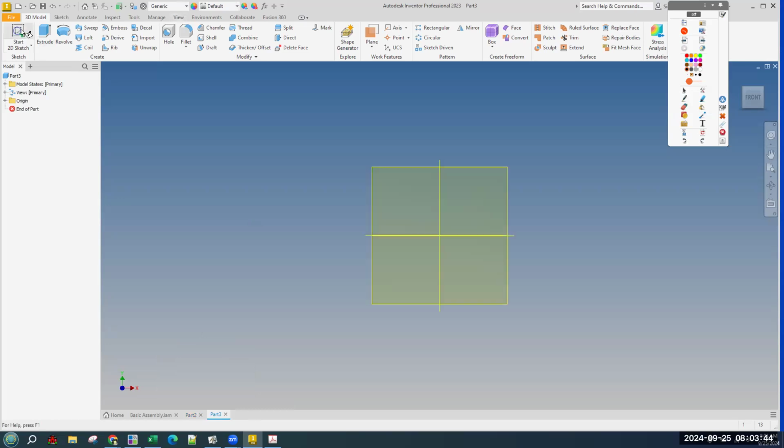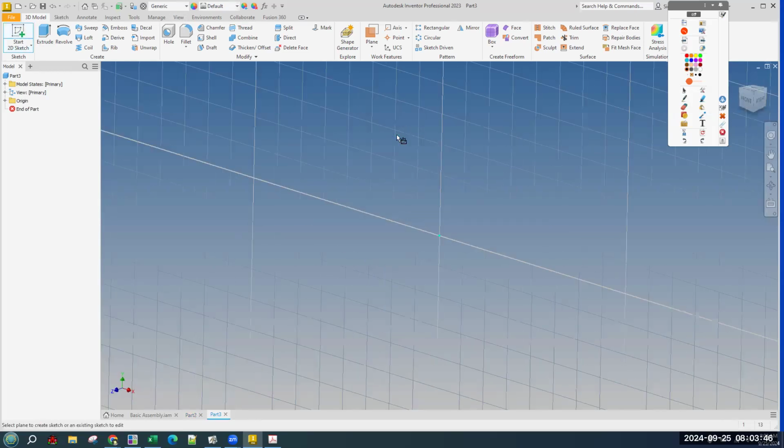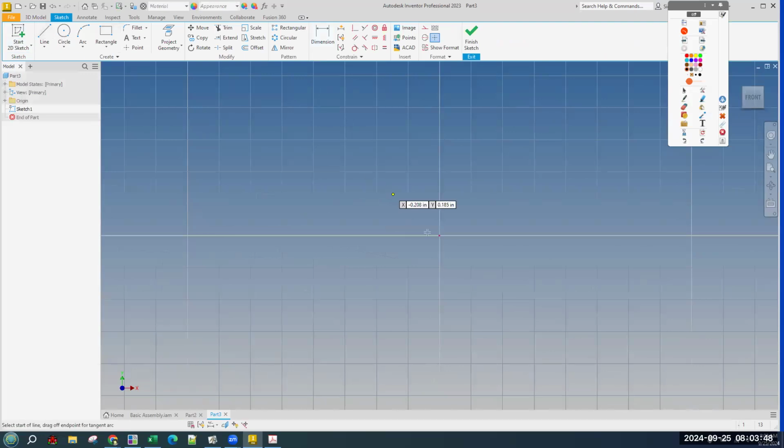Okay. So start a sketch on the XY plane just because. And we'll start with our vertical axis. So from the origin, just go straight up. And right click OK. And like I said before, all of our revolves, we're going to plan by sketching, taking note of what we're going to end up spinning around.